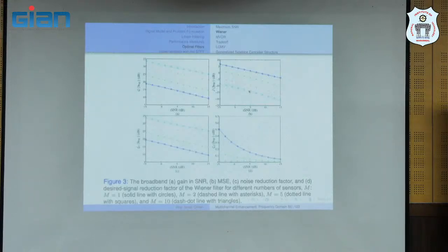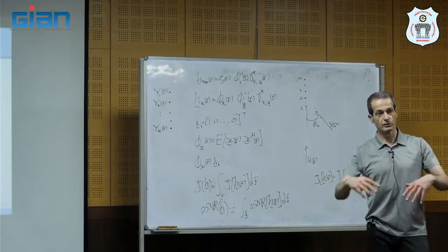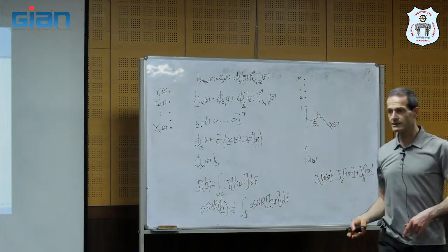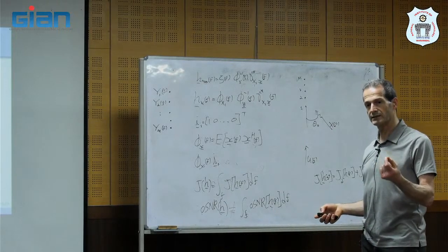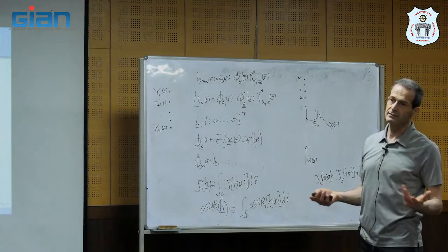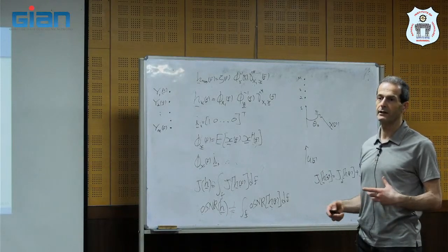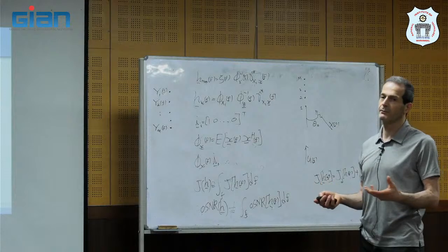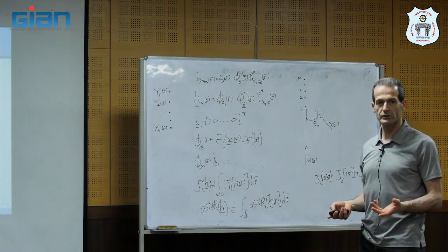comes from a certain direction, if I will have noise, thermal noise, or diffuse noise that comes from all other directions, the amount of performance when we move from 1 sensor to 2 sensors is not as big as this. Okay, so the jump in performance will be much smaller when we deal with thermal noise or diffuse noise.